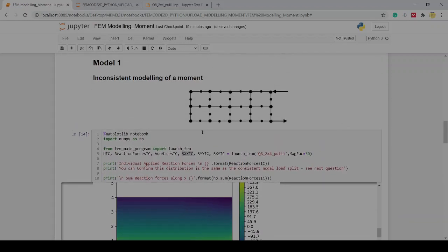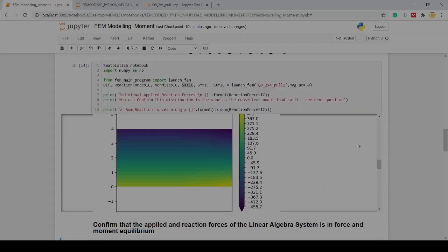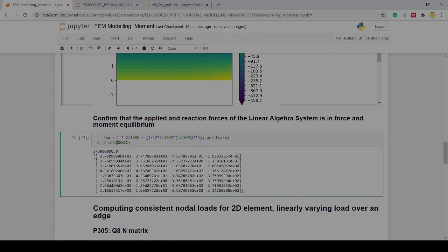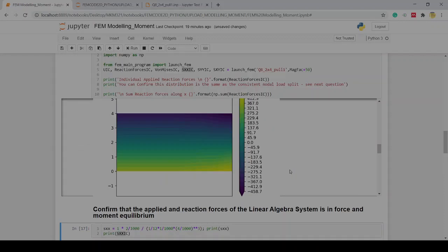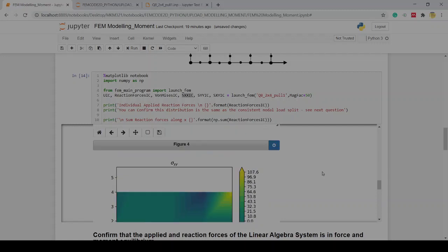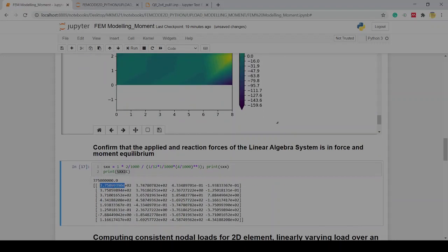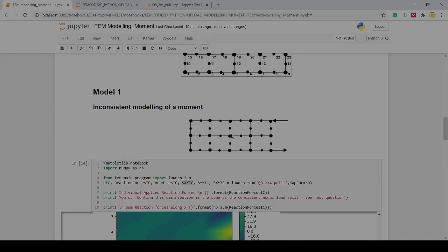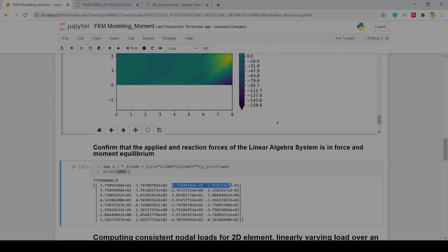That is now for this element right down here, at node 1 of element 1. So I'm looking at sigma xx, at element 1, which is our first element, and at node 1. Then nodes 1, 2, 3, 4 would be these values that we see here. Make sure we are clear on that. We can see that sigma xx on this center, the neutral axis line, is essentially 0. It's close to 0, a very small value, 0.4 and minus 0.2 MPa. That's really cool to see.